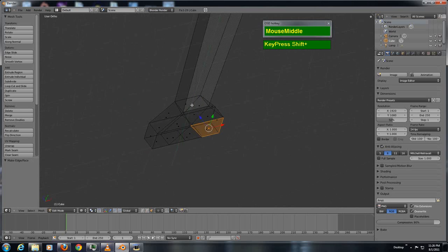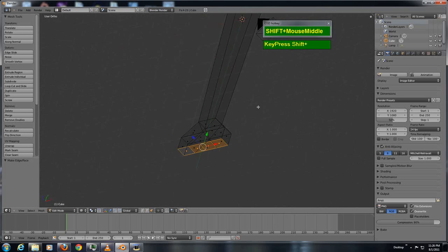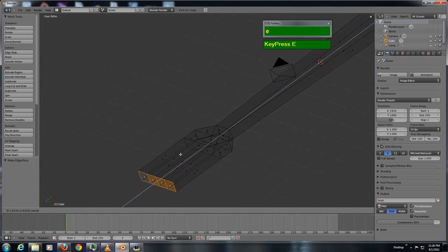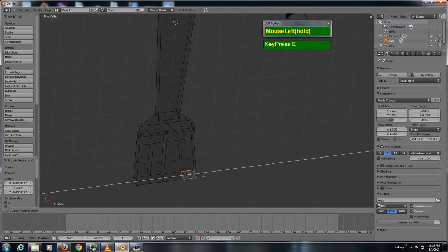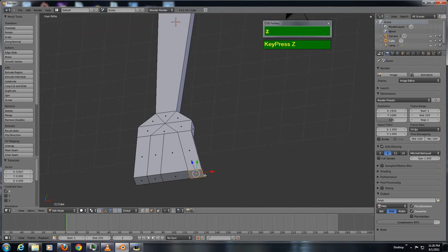Next, what I want to do is select these 4 faces and start to extrude the prongs of the fork. Now, if I were to just press E and extrude right now, the problem is these 4 faces are going to behave like a single object. See, they are stuck together. Okay, let me go to shaded mode, and you can see that the adjacent faces are stuck together. Alright, so that is not the result which I want.